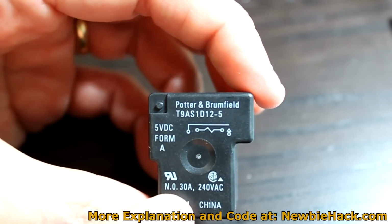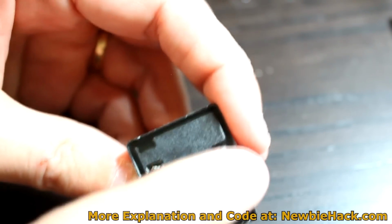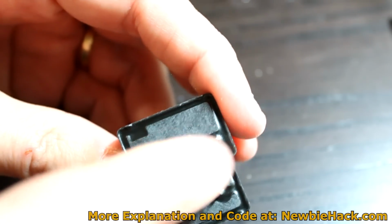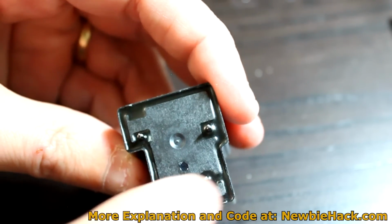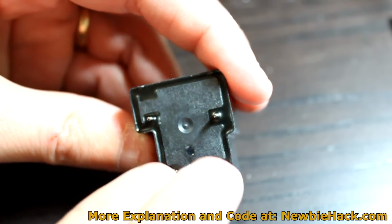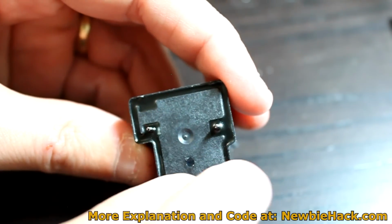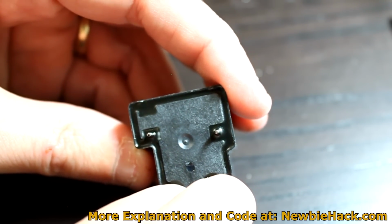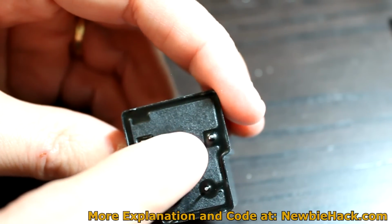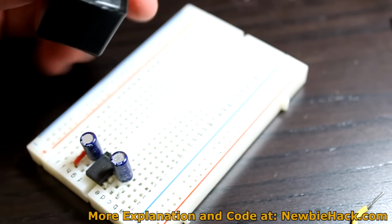So when you apply the 5 volts, it closes the switch and creates a connection between these two pins. These are the two pins that are considered the contacts, and these two pins are considered the coil. So you apply the ground and 5 volts to these two pins, and these two pins will connect together. If you disconnect the 5 volts from these two pins, or apply 0 volts, then these two pins would be open or not connected.